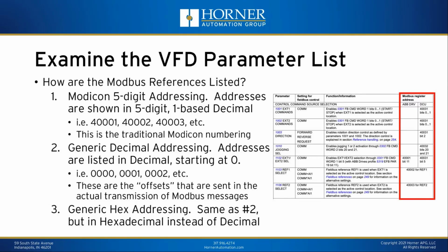And then you're going to continue to take a look at those parameters, not just from the standpoint of scaling and where they're located, but from a Modbus standpoint. Again, we're talking primarily Modbus here. What is the Modbus address that I'm going to use on the OCS side to be able to access these parameters? There's a variety of different ways in which Modbus data is presented in the user's manual. Now, when I show you the OCS configuration, hopefully you'll see that we've done the best we can to make what you configure on the OCS side from a Modbus standpoint match what the drive has listed in its manual. So we've given you some options on the OCS configuration end to try and make things match.